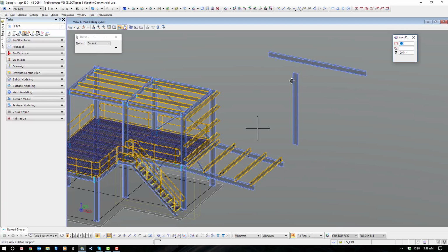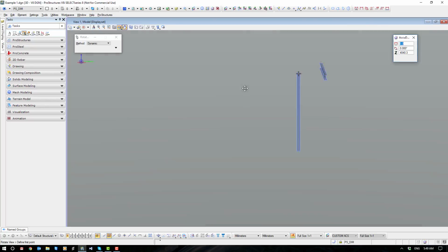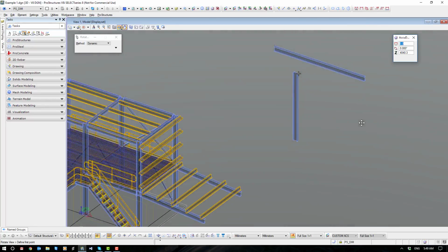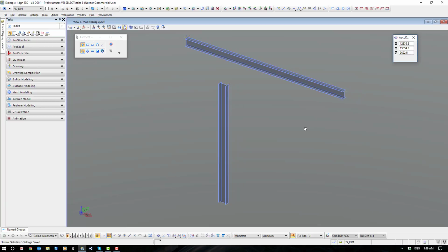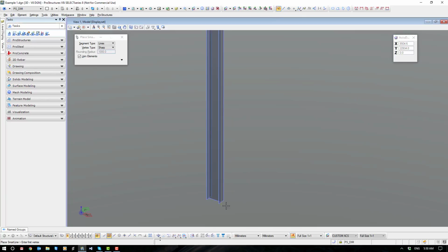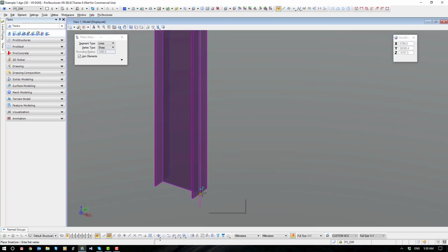member. So I'm just going to spin this around a little bit here, and you can see they don't line up. Now the reason is I'm going to put a compound brace between the two, which is about as tricky as we get in structural steel. So I'm going to kick off by just drawing a construction line to work on, again using the skills that we've learnt up till now.